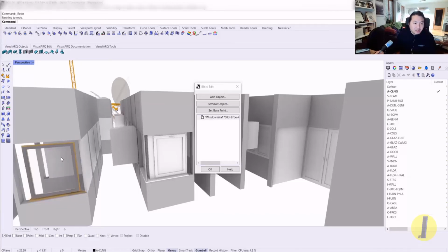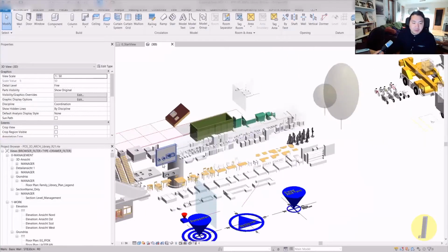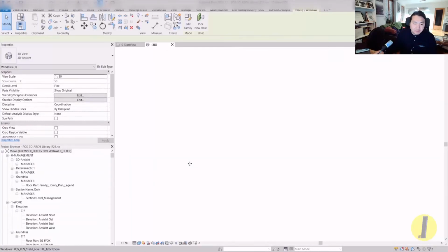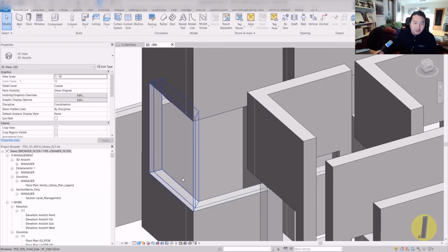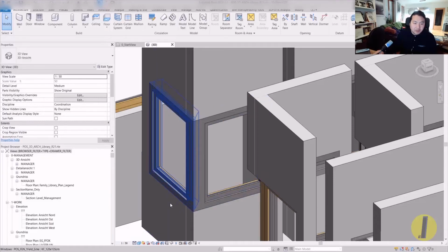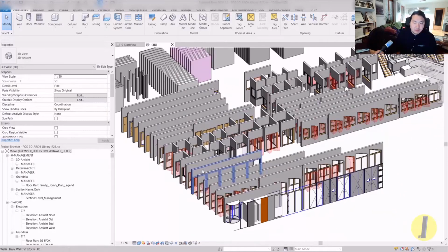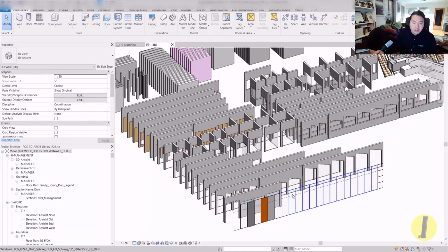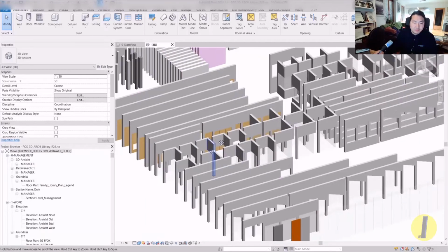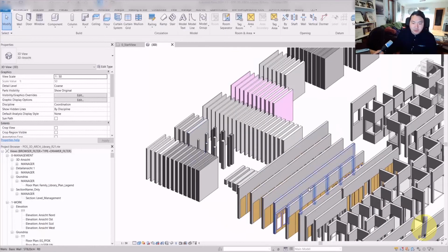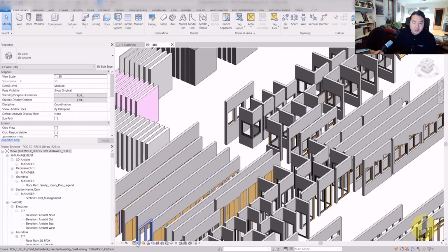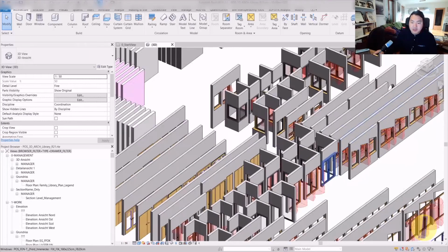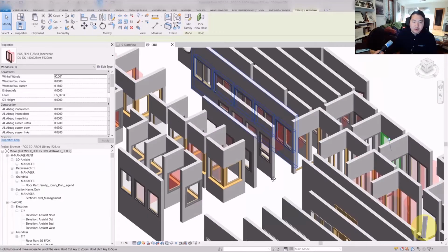Again, you see. So this happens because in Revit, it's clear because we can control this level of detail based on coarse fill. Then it shows only the panel, and when I go medium, a little bit simpler, and also fine, then you have a little bit more detail, which applies in my case for all the elements. So all the doors or windows, they simplify when it's the low level of detail, and medium it increases. When it's fine, then it even increases and shows the volume strategy of door and window openings.